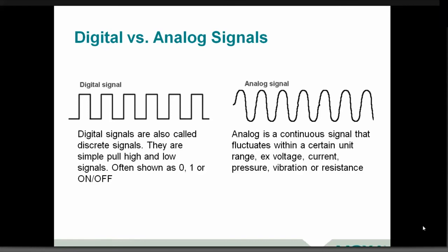When we talk about I/O, we're talking about really touching those sensors and actuators inside of a system at the furthest reaches of a network, right? We're pushing out to the network edge, and there are two fundamental categories for this: digital devices and analog devices. Digital is on, off. Is it running? Is it stopped? Is there an alarm, yes or no? Whereas analog is things like, what's the current temperature? What's the pressure? How high is the level within the tank? And we get kind of specific about some of these things. So categorically, those are our two fundamental ways of characterizing I/O.